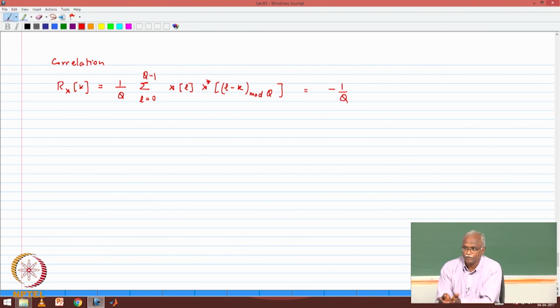That is exactly what we have been able to achieve. At least from a correlation point of view, these pseudo random sequences actually map to the ideal case, but the only thing is I am not doing linear correlation, I am doing a circular correlation, but it is very important for us to know that. And please do look up the basic proof of this correlation property.